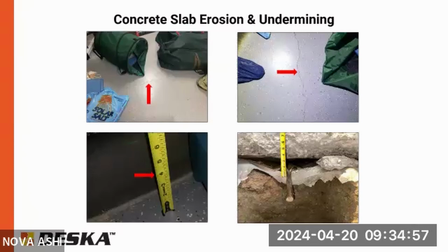So just because these cracks in the slab are not a structural concern, they often point to a larger issue. And just keep in mind, you can only say what you can see. There's a lot of things you can't see. So kind of going back to the inward deflection of the foundation wall, sometimes you can only see a little area, and the basement's finished. Maybe the soil is too high on the exterior. You can't see much, but sometimes just these little symptoms can turn out to be a big problem. So I'd always just be very aware.